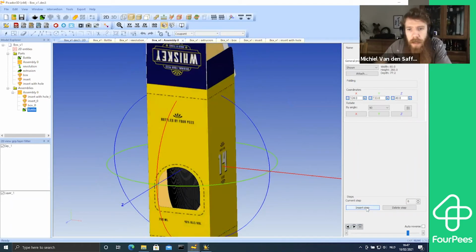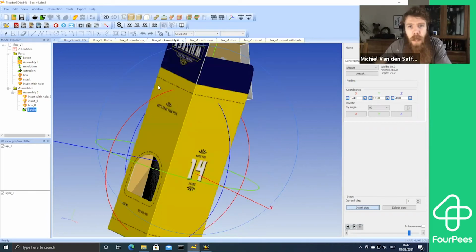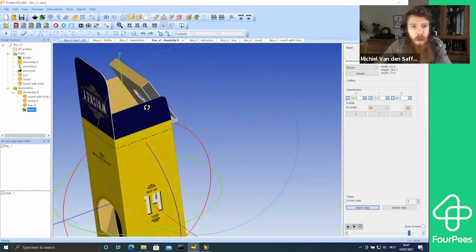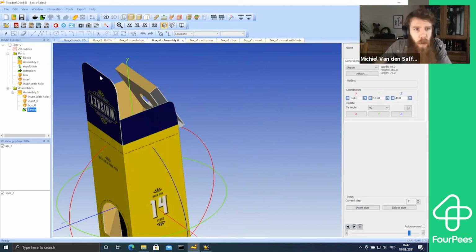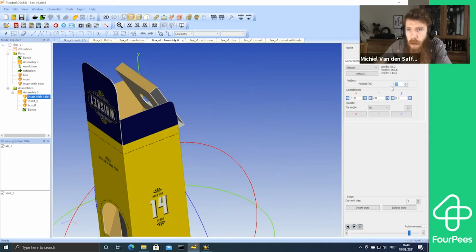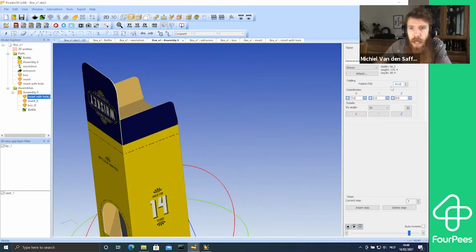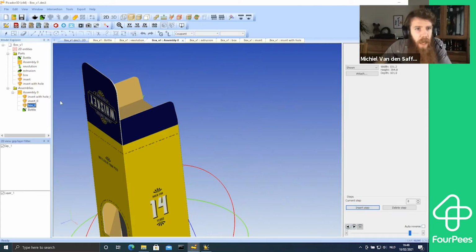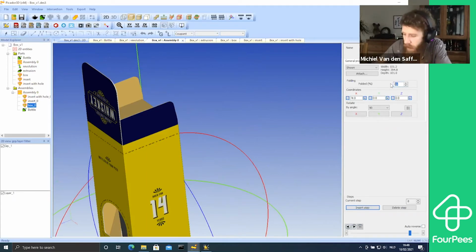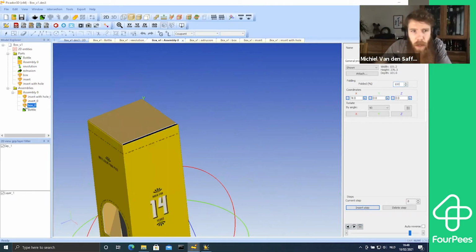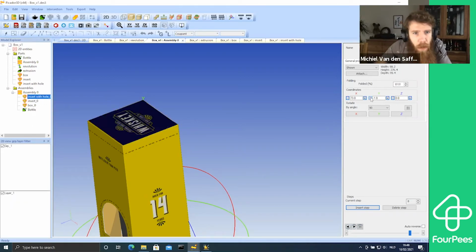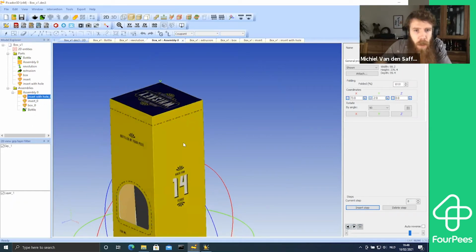And then in my next step, I can close up the top here because I still had that folded up to get that box inside. So I'm going to grab my inserts again, and I'm going to say, now you can fold up to 100, which means the top goes down. And I'll go another step and I'll grab my box again, and I'll say, now you can fold up to 100, and that will close the box. Oh, it looks like my insert is a bit too high. Let's get that down inside my box. There we go. So now my assembly is done.